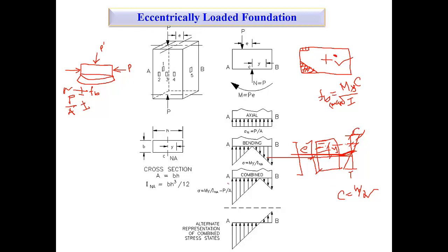Okay. Then what you can do, you can replace this C equals H by 2, right? Can you replace C equals H by 2? And this I equals BH cube by 12, right? Can you replace it? So if we cut this portion, it would be 6, right?